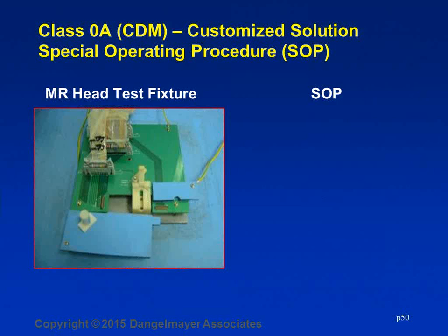The capacitance of your device is governed in part by its distance relative to ground. So if you change the elevation of the device, you will change its capacitance and therefore the voltage and therefore the stress. The other scenario is to do the discharging as close to the test connector as possible to minimize movement and recharging. So it all makes sense to put this connection or this display pad here.